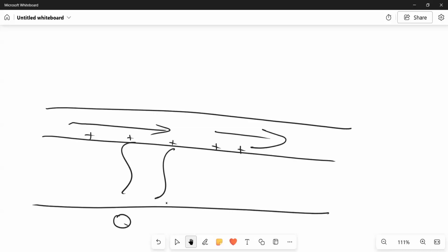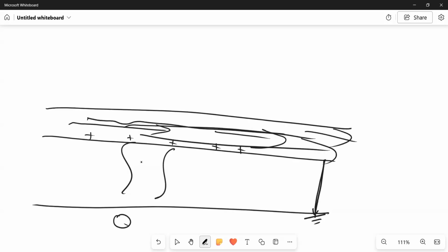So what they'll do is ground this pipe somewhere. They'll connect this pipe to the earth with a grounding wire, so that any charge that builds up in this pipe will discharge itself to the ground. You'll find that if there's a pipe or some chute that grain is sliding through, maybe rice, it's sliding through.